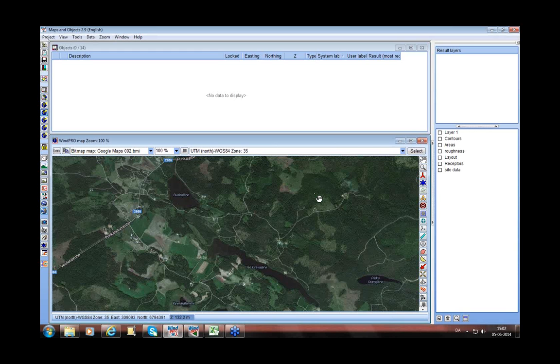This is a webinar that will introduce you to the NORD2000 calculation model in WindPRO and show you briefly how it works and what you can get out of it. NORD2000 is a calculation model for noise modeling, which was originally developed for traffic noise. It was a few years ago validated for wind turbine noise, and we are using a calculation engine from Delta in Copenhagen, Denmark, that we call for the calculation. So you operate NORD2000 from WindPRO. It sends the data to NORD2000 and it returns the result to WindPRO again for presentation.